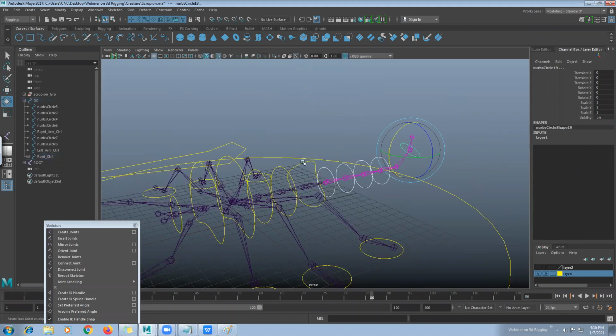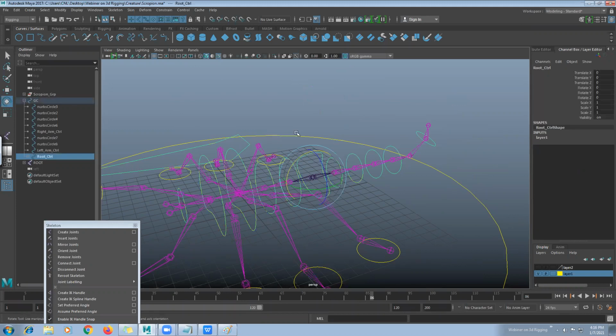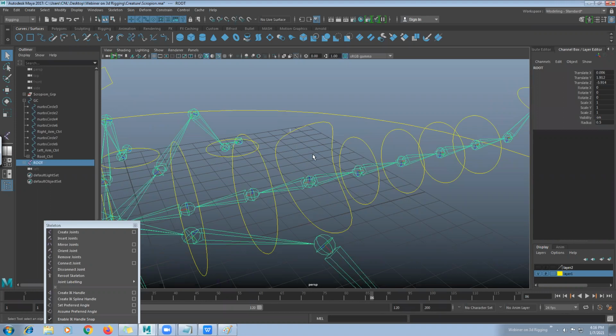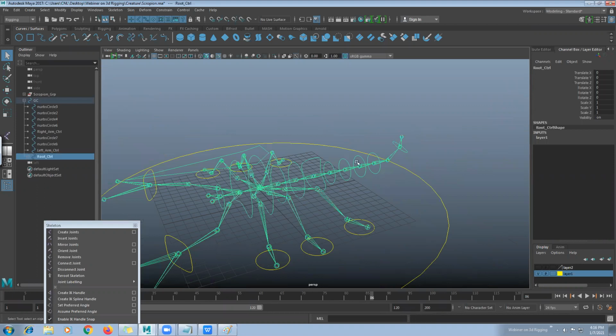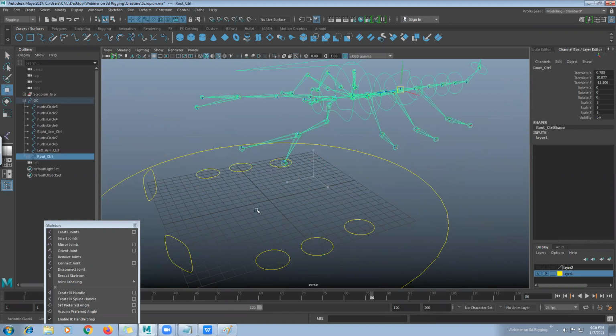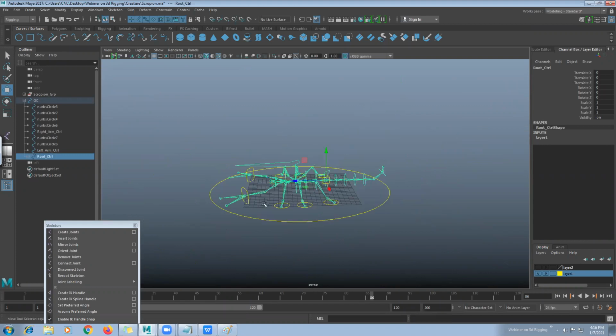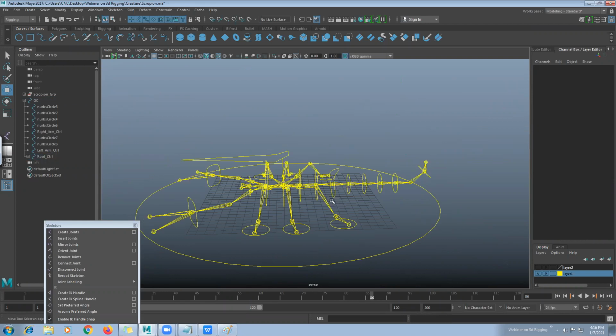Now we should place this empty because we're going to parent it directly by pressing P. So select this bone and select this and hit P. Now what happened inside that particular thing, everything is parented. So if I move, everything is moving, see, except those features because those are connected with the leg. So whenever you want to connect it with the leg, it's a different approach.